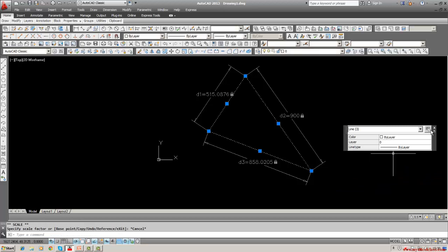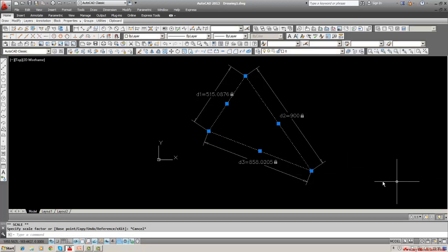That is because these constraints should be the same. This fixed constraint we have applied at this point should remain the same. It cannot change its position. Line N should always be in contact with the other line. This line should be in contact with this line, to be in contact with this. So when we move one of these points, along with it, the contact also remains, and the entire triangle moves. It can rotate also as such.